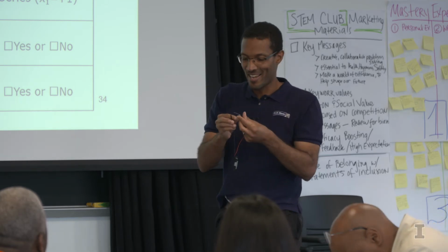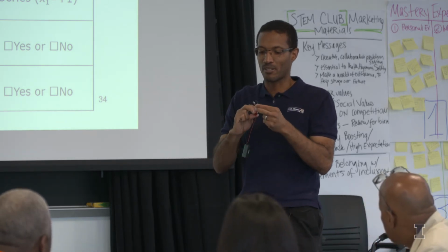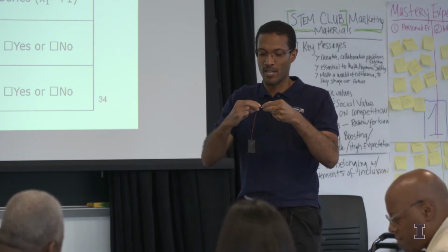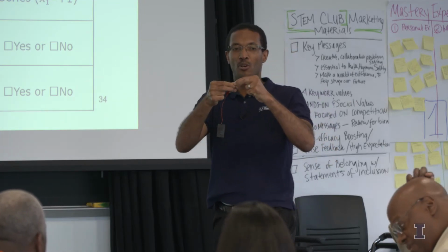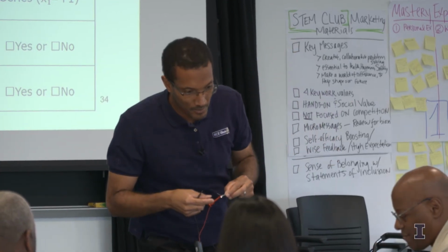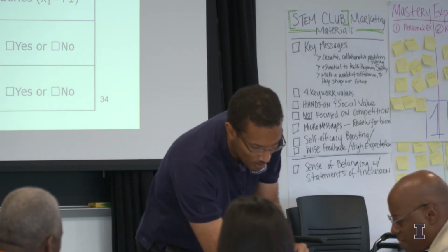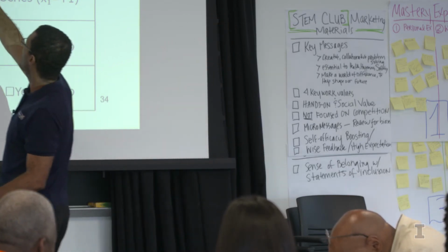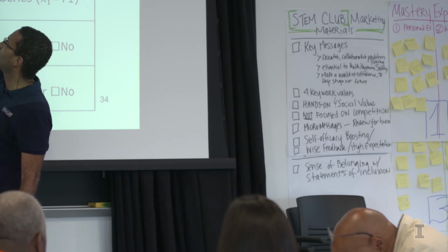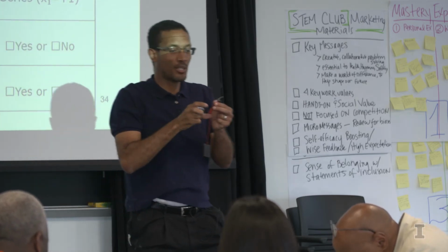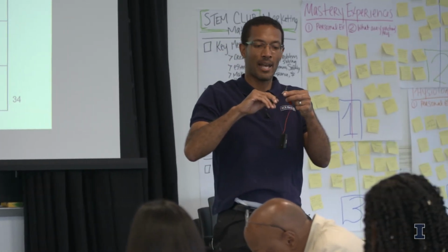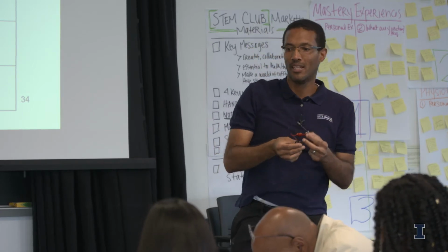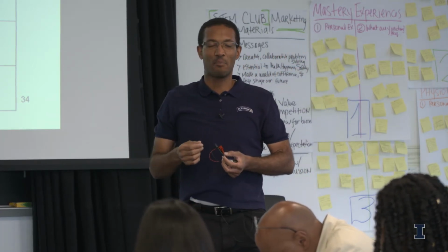All right. And then, oh, I clipped it wrong. Oops, sorry. I clip the resistor and the short leg of the LED, so I need to clip both of them. So question? So you have the short leg, and then this also needs to be clipped. So these two together, clipped together. Yeah, so you're clipping both the resistor and the LED onto the short leg with the red clip. And then you clip the long leg to the black and to the resistor together. And you see, does it light up? And in your notes, you'd write down, yes, it lights up, or no, it does not.